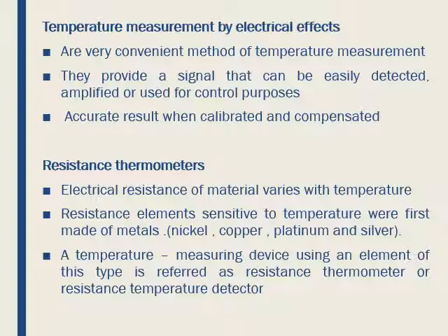The higher the range, the higher the cost. For temperatures up to 450 degrees Celsius, normal glass is used. At temperatures above 520 degrees Celsius, borosilicate glass is used. Above this temperature, quartz thermometers have been used, but they are not common.